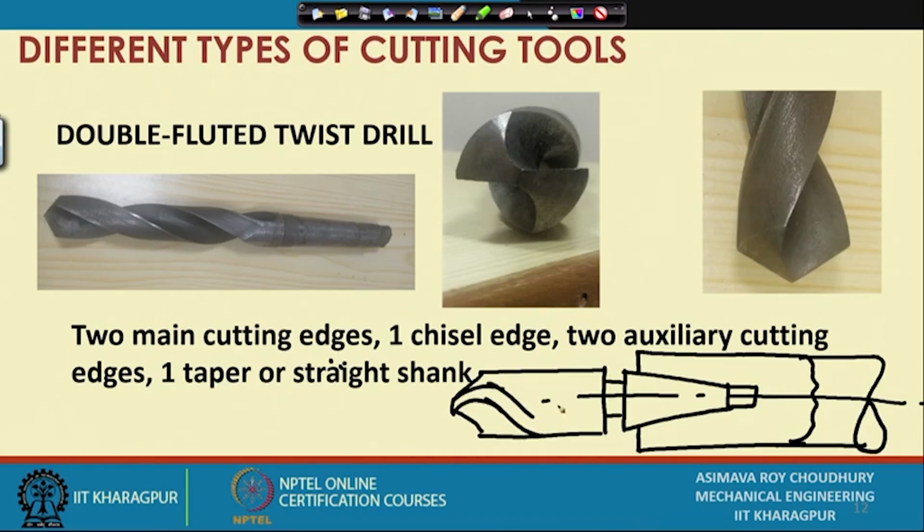The drill has this conical portion which fits with another conical hole, so that the axis of the spindle and the axis of the drill coincide due to one cone going inside the other. That is, locating the drill is done this way.